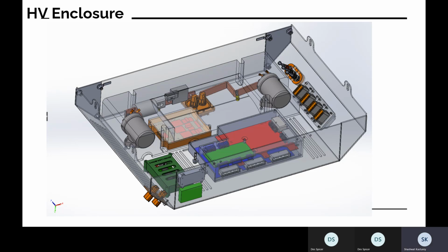Those are the accumulator isolation relays. We have a bunch of bus bars. These are just bent copper sheet that conduct electricity. Way better than cable for this use case because you can get into much tighter spaces with it. I don't think it gets as hot, especially because it's open air here, dissipating heat. And in most cases, it's safer and easier to package than cable within a battery pack.